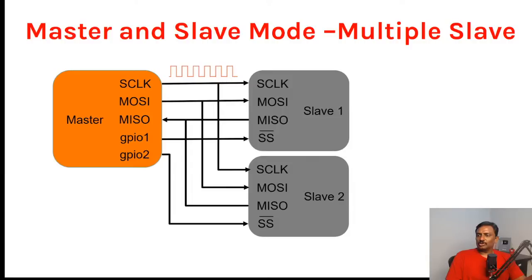In UART there are two types: one is clock based and another is without clock, synchronous and asynchronous. The most widely used one is without clock. In that case, you have to maintain the baud rate. Both the transmitting device and the receiving device should be on the same baud rate, since there is no clock and it's just a timing waveform, so they need the same frequency to receive the signal.